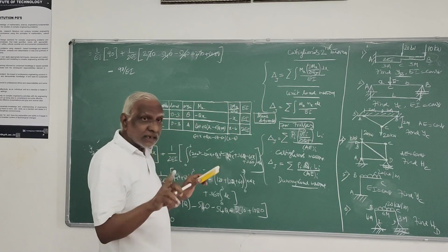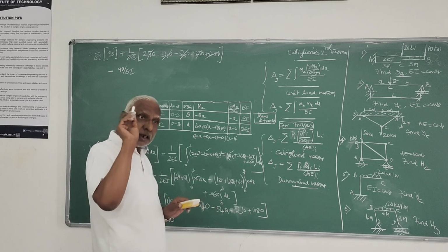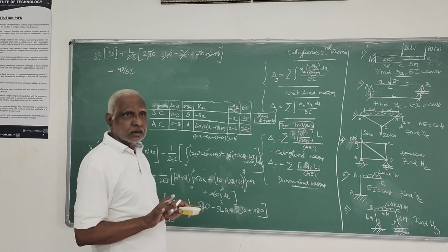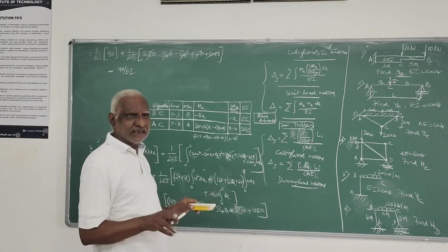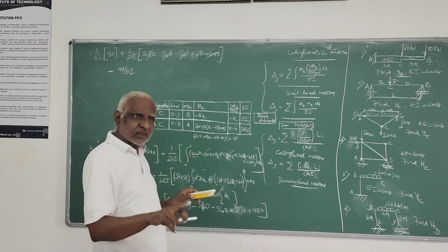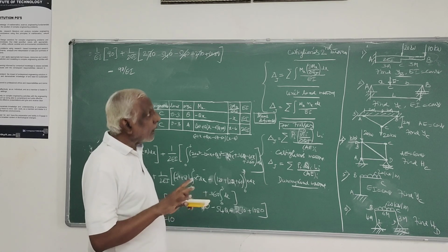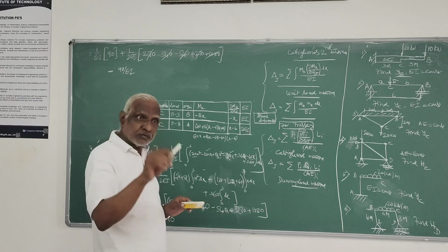Where deflection or deformation is required, there only you have to apply Q. No, sir, I am talking about slope. If we compute slope, we have to apply a moment load. You have to apply a fictitious load, and that fictitious load is a moment load. If they give a moment at C, and if they ask you to find the slope also at C,